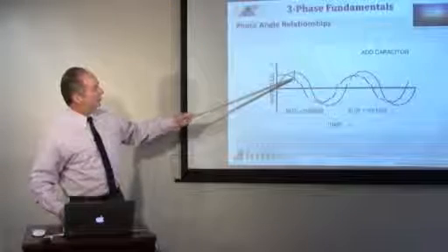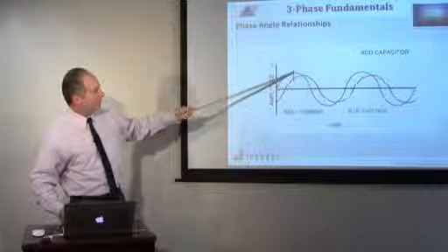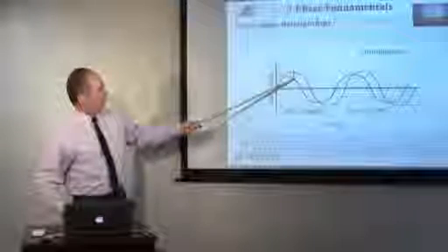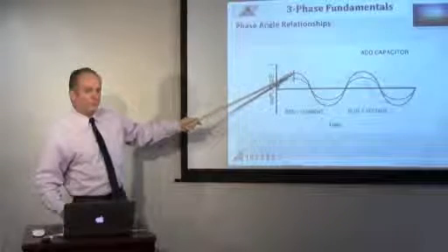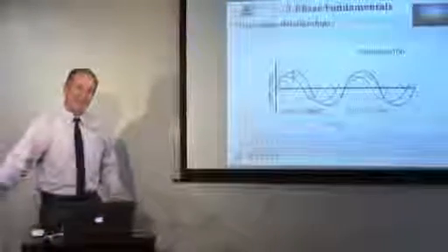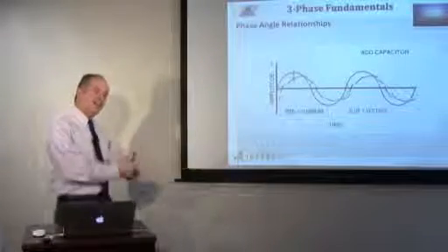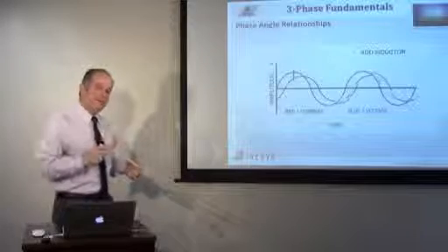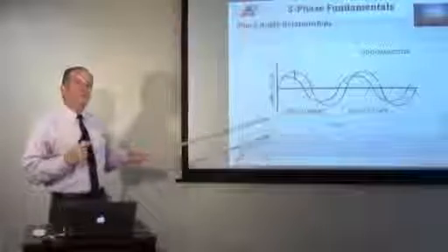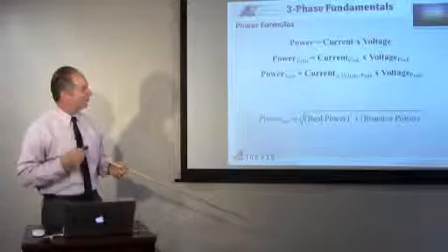So the main factor here is this is the current we need to produce so many watts. If we had a 100 horsepower motor, we would have this current at peak voltage, but it would draw more current because it's lagging. So we have a higher current so that the current at the time of peak voltage is the 100 horsepower. We're running a higher current than we need. If we could add capacitors, we could balance this out. That's the idea going on in the power system.